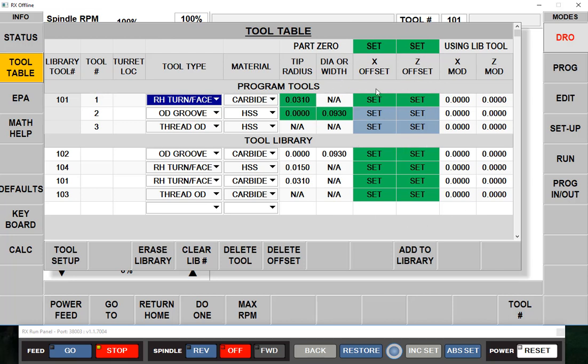So does your first tool. And now I have two more choices. Either reset these two manually so they turn green, or select one from my library like I'm about to do and use the green tool so that I know everything's correct. I should never go to the run mode if any of these tools are a different color. Okay? Next thing I'm going to do is show you another scenario on how to get it back.